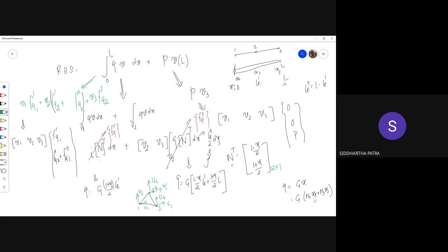So when I say components of the u vector, I have U1, U2, U3, U4, U5, and U6. And you realize that U1, U3, and U5 are in the X direction, and U2, U4, and U6 are in the Y direction. So the components here do not mean direction. Component is just a numbering. And that's what the finite element method is: keeping track of your degrees of freedom.